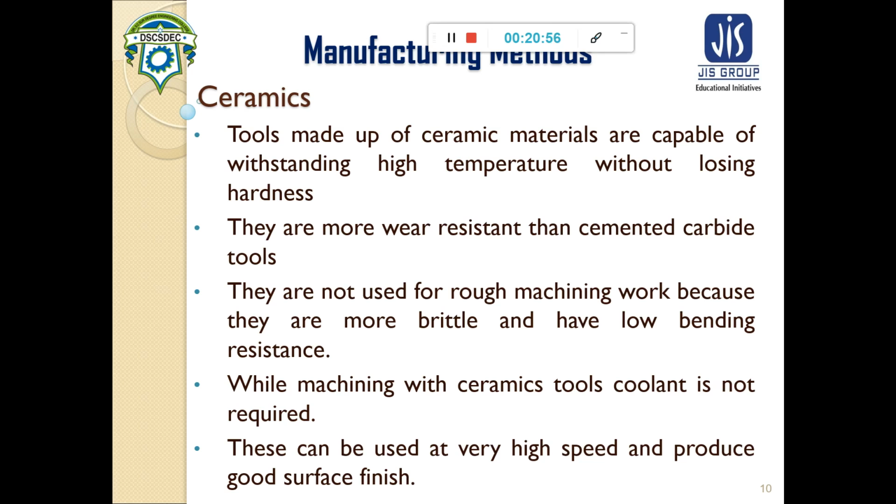While machining with ceramic tools, coolant is not required, so we can use the dry machining technique. The details of dry machining we will study in the next lecture, that is cutting fluid.